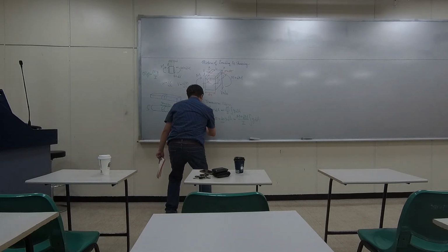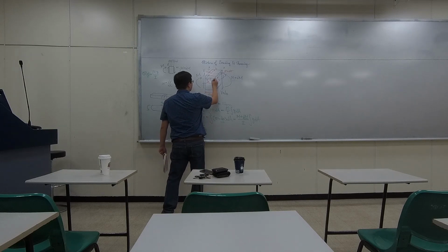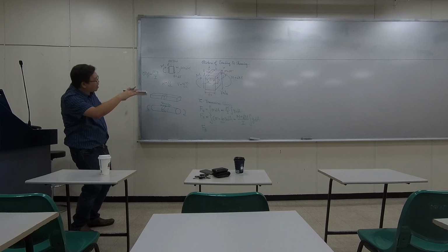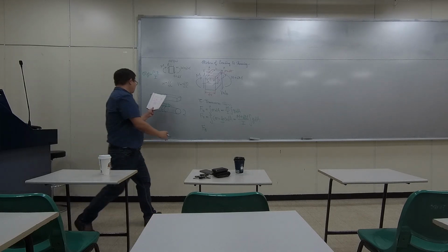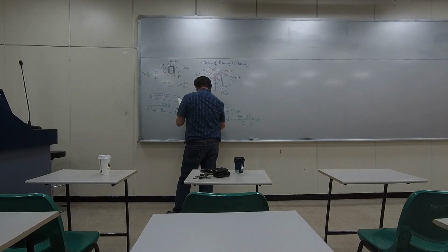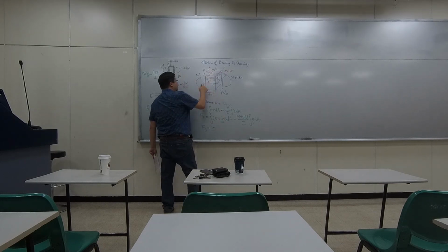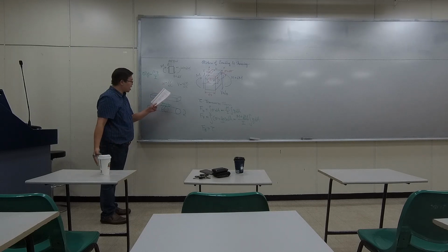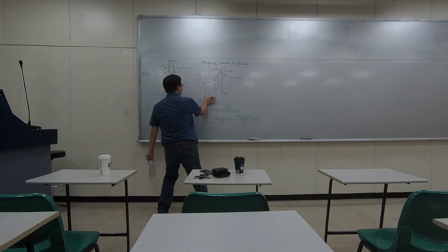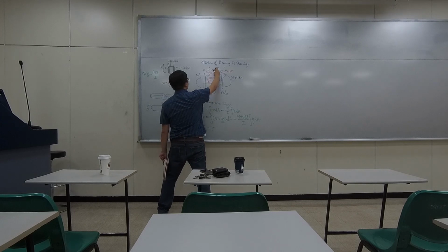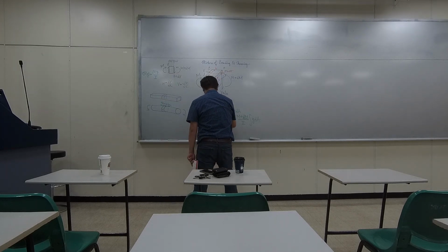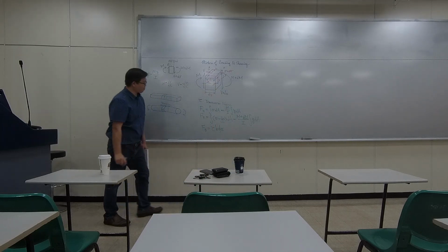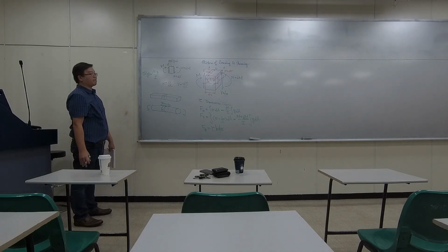So here there's an Fb. B represents bottom. Okay, so lying on that plane, Fb would be the stress that you're looking for multiplying the entire area. So the area would be the width right here times the thickness right here. So it's going to be b dx. Right? So there's a balance between them.